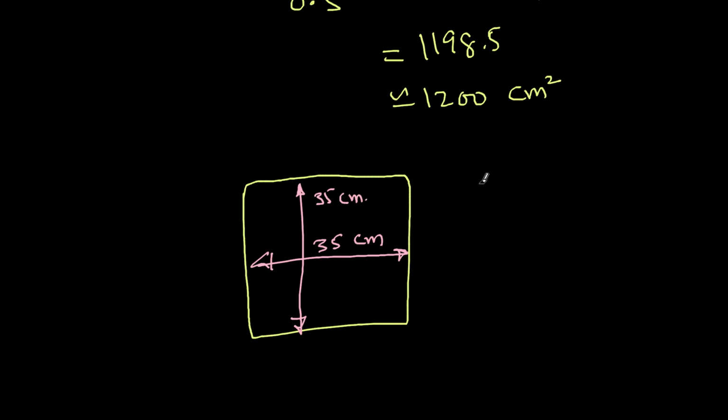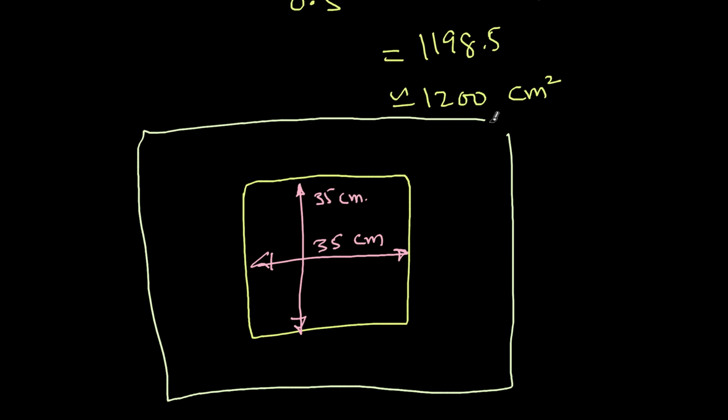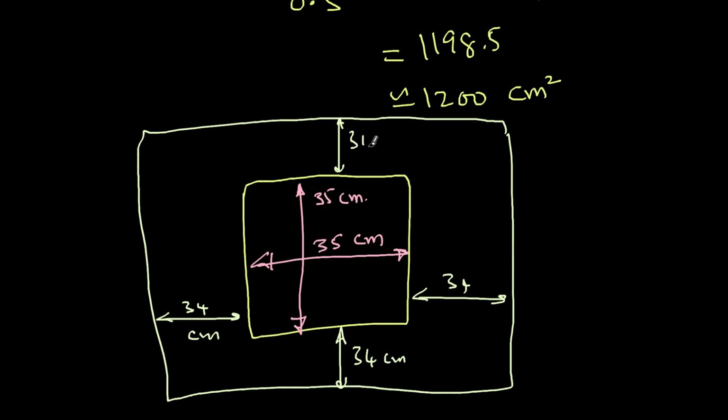Then additionally I require 34 centimeters for the core all the way on all sides. So this is the square cross section for the core, and the side is 34. So ultimately we are now getting the dimensions of the transformer core. So this is how the calculations are done to design a transformer core.